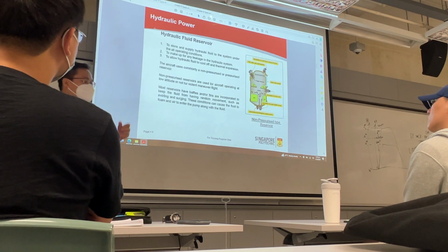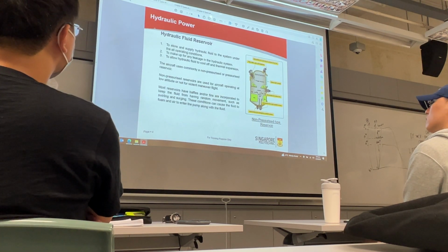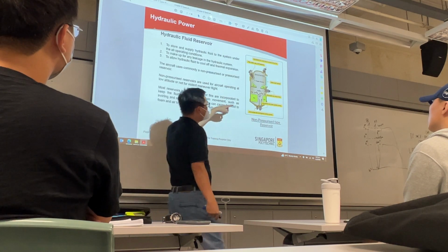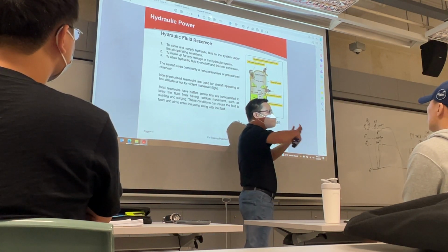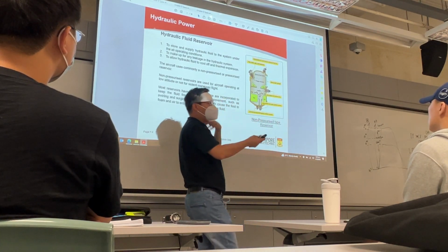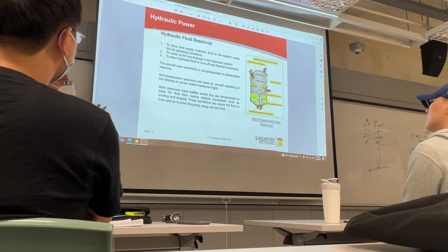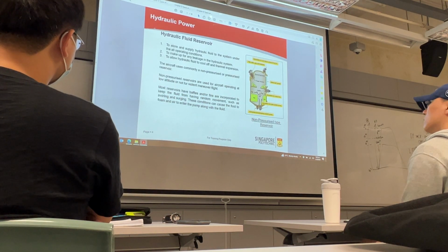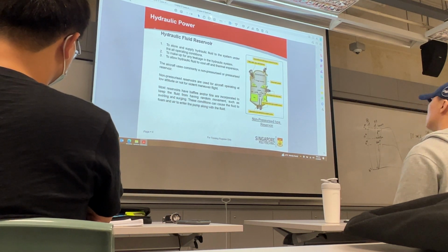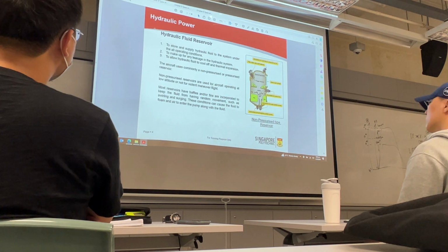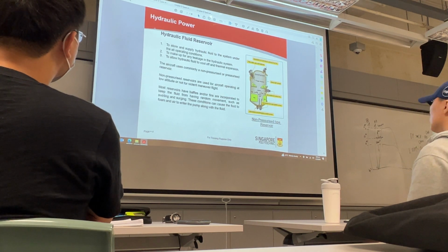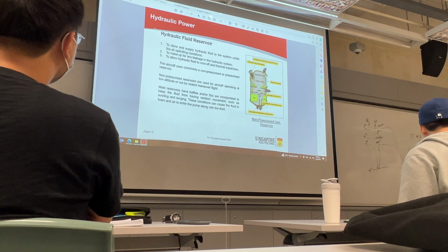Air. Correct. So, when the fluid goes back in from the return, if it starts to swell and whatever, what happens to the fluid? There's a lot of air. There's foam, it goes into your pump, and my pump suffers more cavitation. This is the reason for that.